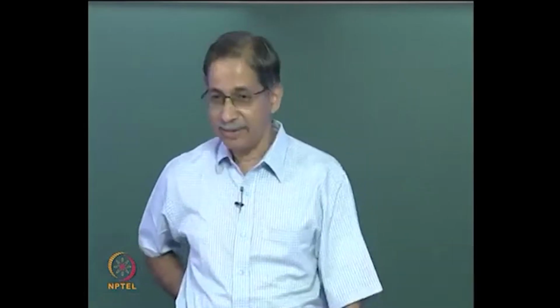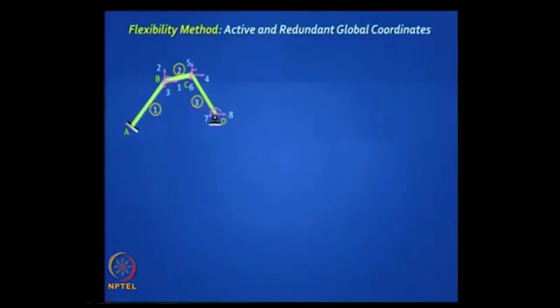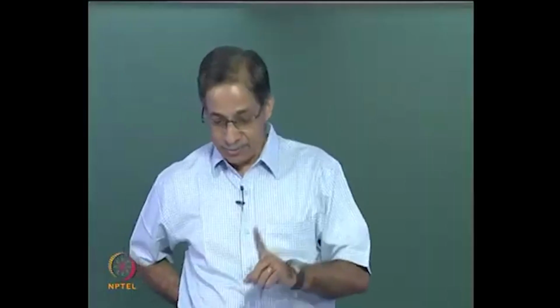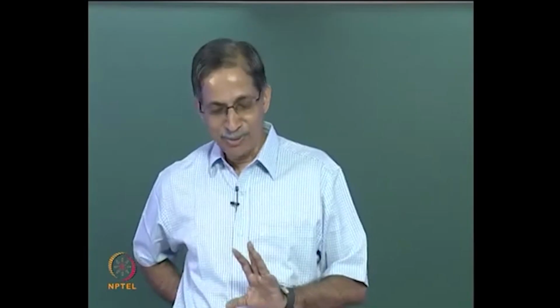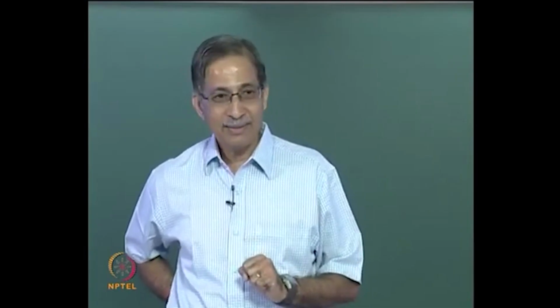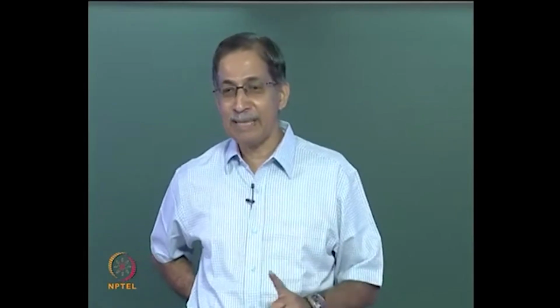Now this particular structure, is it statically indeterminate or determinate? Indeterminate. What is the degree of indeterminacy? 1. Which would you like to choose as a redundant? The support is not the redundant, it is a force. So corresponding to that redundant support, you want the primary structure to be a cantilever. That means you want to get rid of that roller support, right? So in terms of statics, you have to replace it with a force, right? And that is your single redundant here.